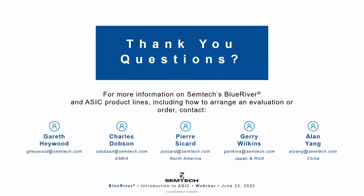That's a really good question. So the BlueRiver philosophy is only to use compression where needed and when it's needed. As a result, basically the compression is determined by the source signal format. So for example, in your question there, 1080p wouldn't be compressed at all because it fits no problem over 10G. The only time compression kicks in is when we exceed the bandwidth of that 10 gigabit network. The compression is fixed at a ratio of about 1.4 to 1.